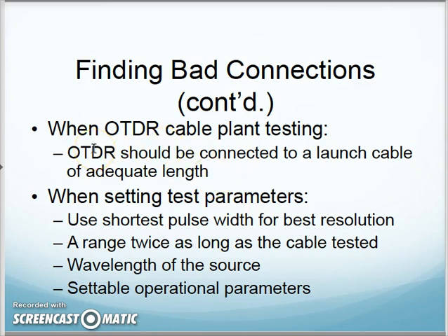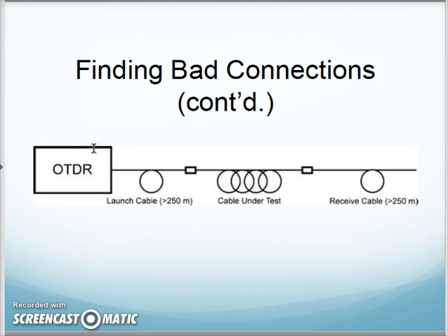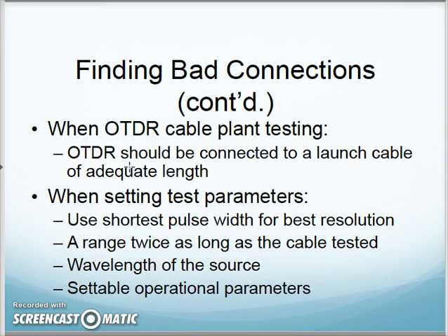Here they give us a couple parameters on setting this up. Should be connected to the launch cable, adequate length. Yep, they even give you some guidelines here about the launch cable needing to be of significant length. That way the light source has time to actually get into the cable and then actually reflect back. If this were too short, everything would be happening too quick and it wouldn't be able to determine distance of things. So my launch cables and my cables to the other end need to be of adequate length for that.